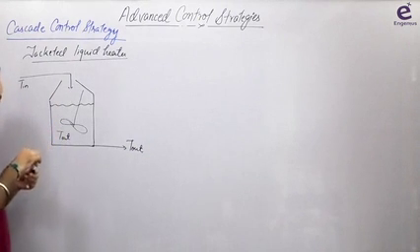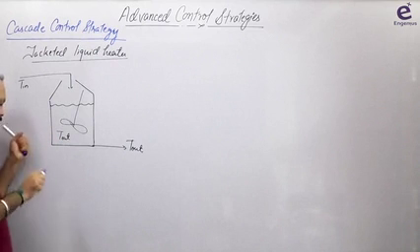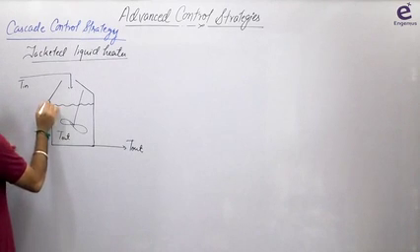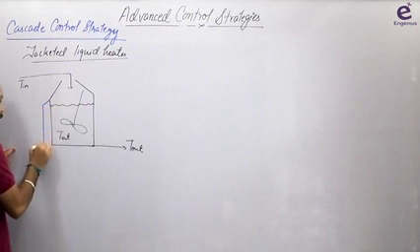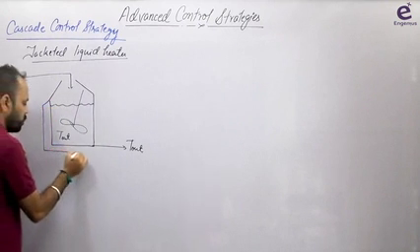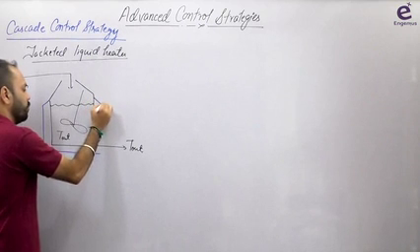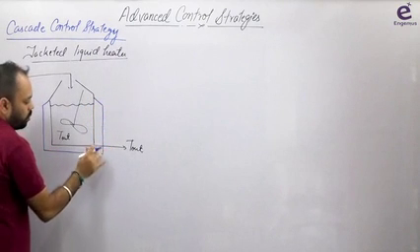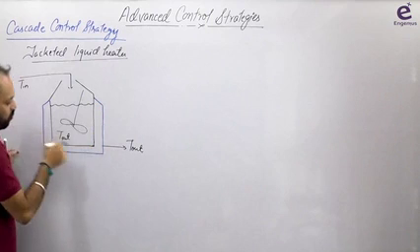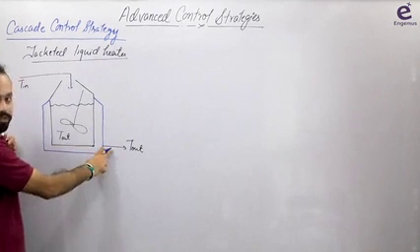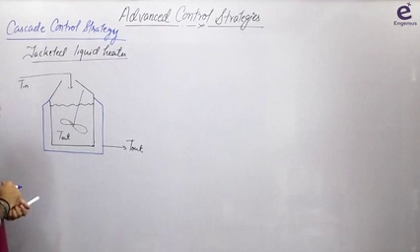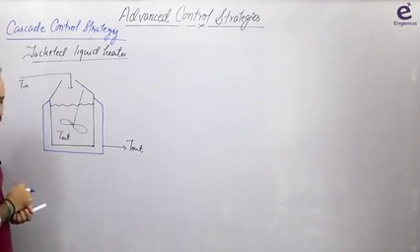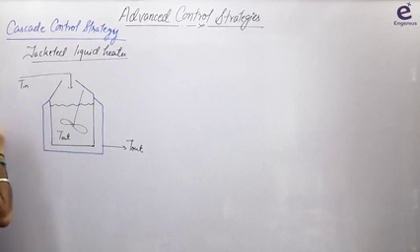How is this being heated? This is being heated with the help of a jacket. You understand what is jacket? Jacket means an arrangement is made which surrounds the entire kettle and a fluid flows through this, and then heat transfer occurs from the fluid in the jacket to the process fluid, right? This is your process fluid, okay? This is called process fluid, okay? Now this heating is taking place with the help of steam or hot oil also, you can say. Let's take hot oil, not a problem. This heating is taking place with the help of hot oil.